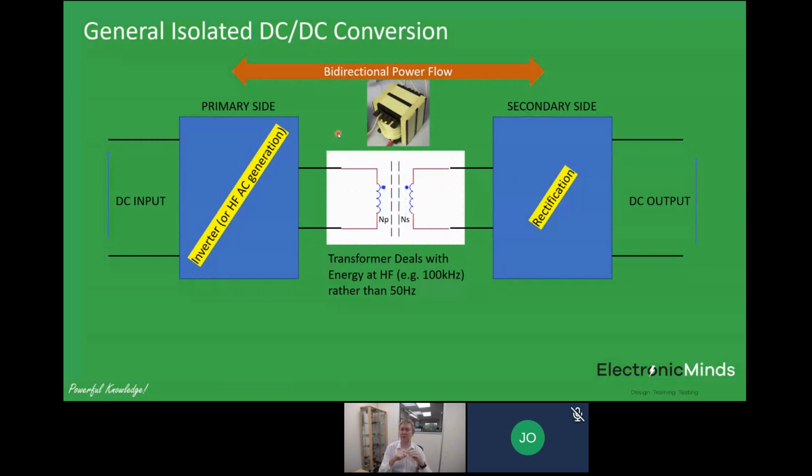And that's quite an interesting thing to do, because when you're looking at e-mobility, electrification of transport, if you're considering electric vehicle charging, well, if you want to support vehicle to grid operation, you need to be able to not only charge the battery, but also have the battery send energy back to the grid should you want to do that. And one of the topologies I'll show you at the end is actually a really neat way to do that at very high performance levels.